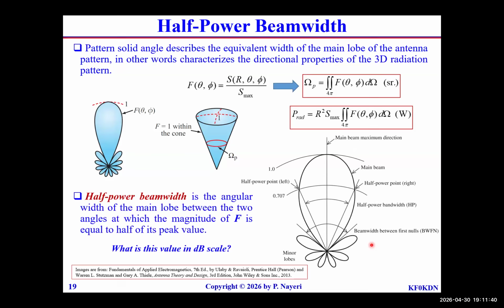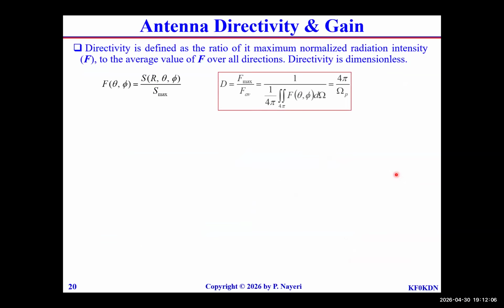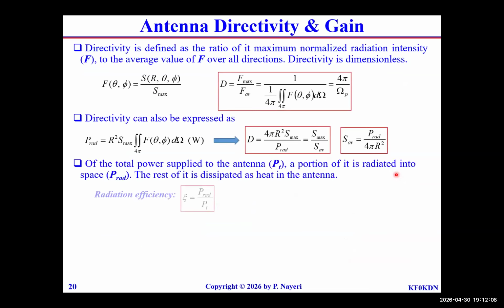So there's a measure which is known as directivity, which is effectively the power associated with the main beam over the power of the entire antenna. This is known as directivity of the antenna. The more directive an antenna is, its directivity obviously increases. Your typical dipole would have a directivity of about 2.15 dBi. And as mentioned, patches may have 7 or 8 dBi, and reflectors can have much higher directivity associated with them.